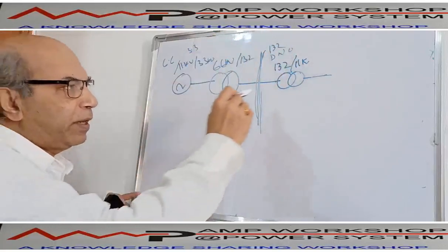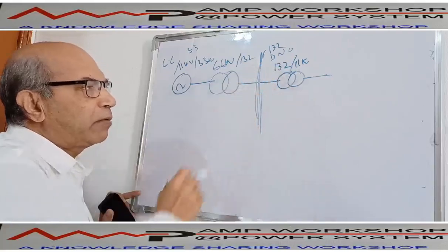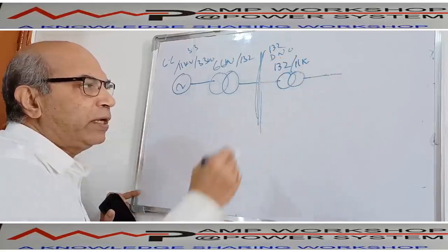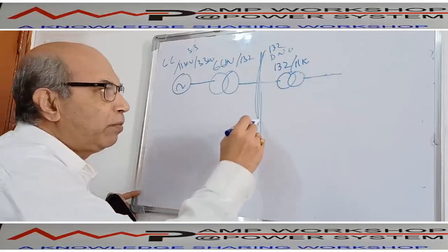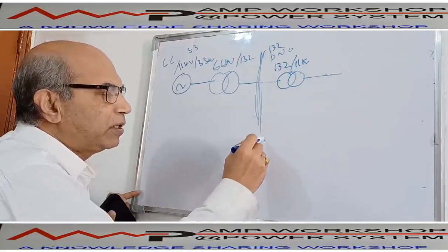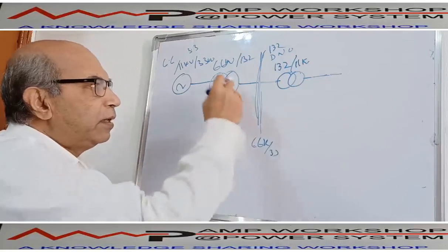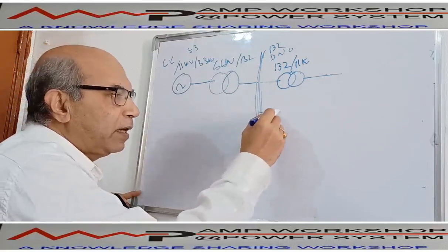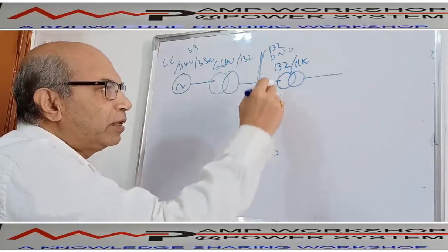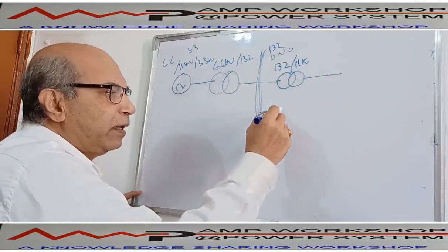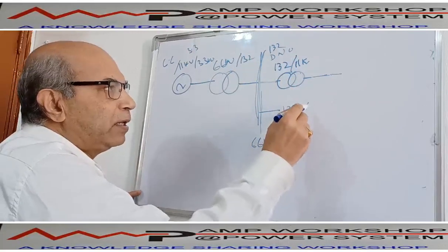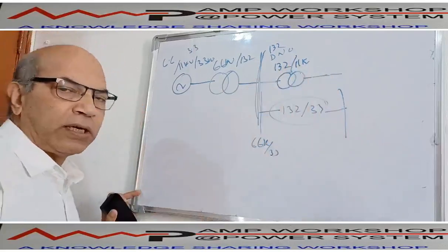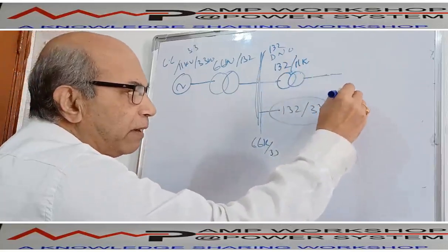This network operator can transfer the 132 kV power and give it to a consumer. There is a consumer over here receiving the power, or instead it could be 66 kV or 33 kV itself. This is how the transmission voltage could be. It may also happen that the distribution network operator reduces the voltage from 132 kV to 33 kV, and then this 33 kV goes to the further switchgear, the 33 kV switchgear. From here they supply power to various consumers.